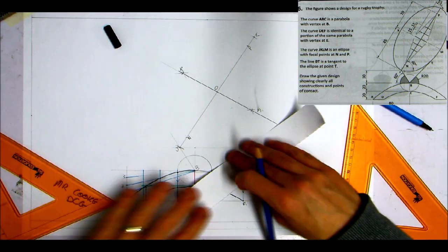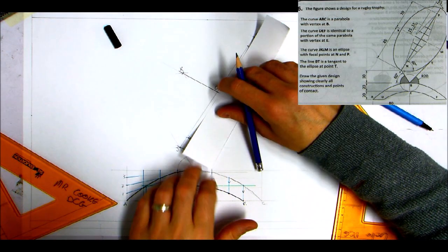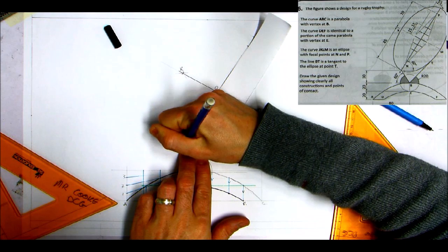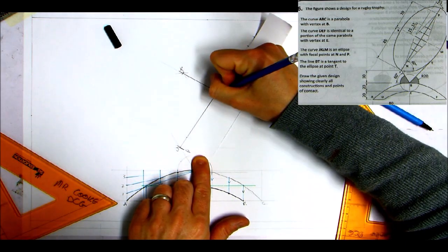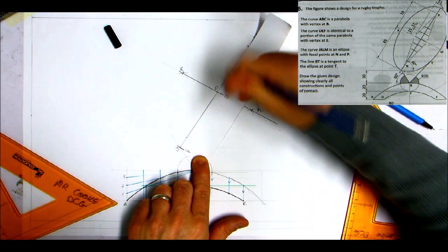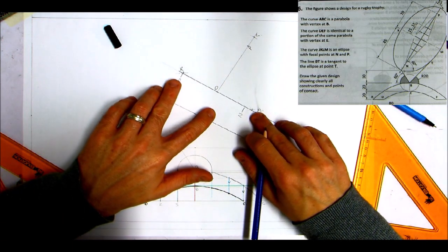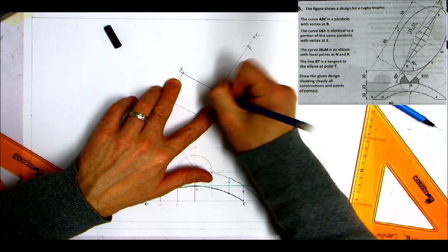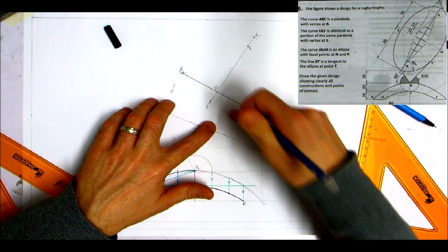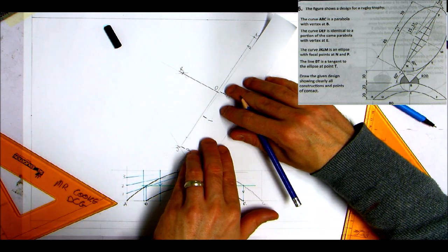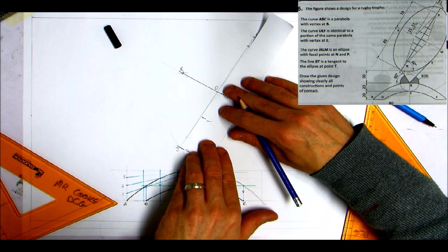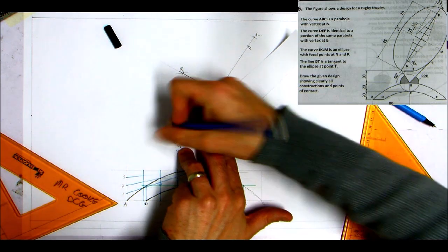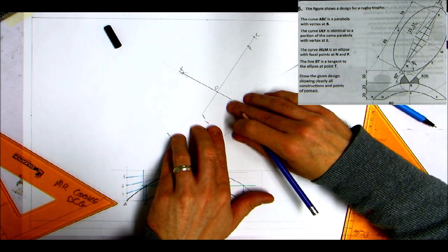And I'm going to mark in the major axis. So this is going to be P, which draws the points. This is going to be 2. And from K to O, or from P to O, is going to be half the major. And as I spin this around, guys, 1 must stay on the major axis, 2 must stay on the minor, and that's how I will draw my ellipse all the way around.